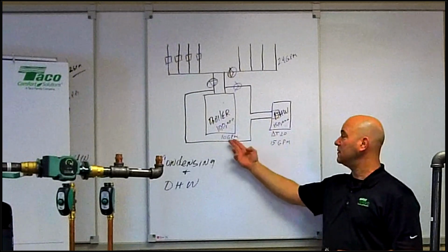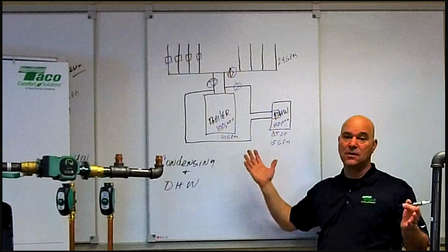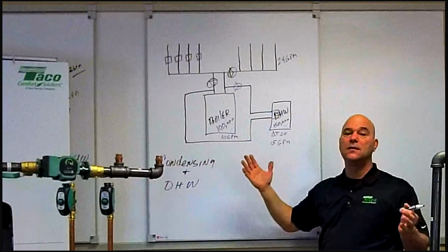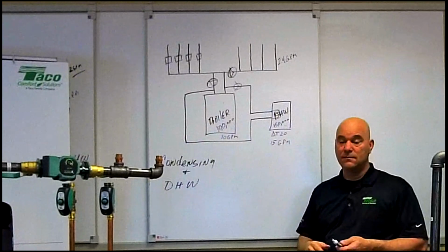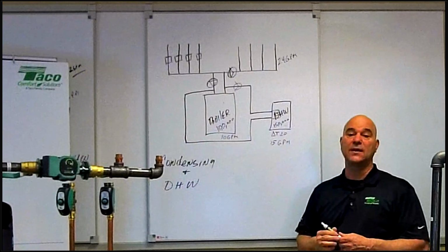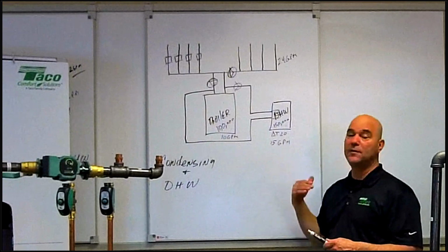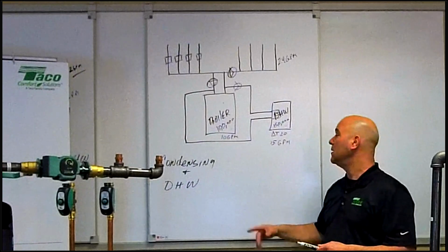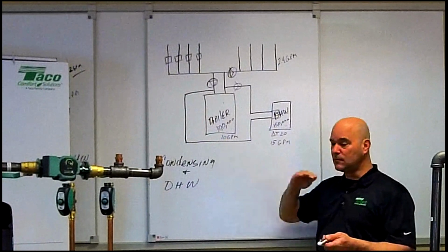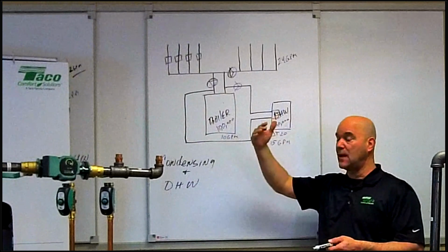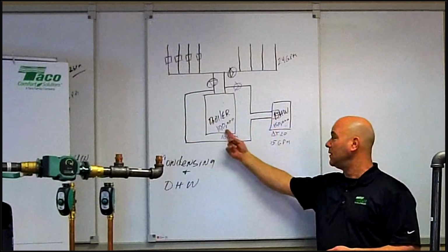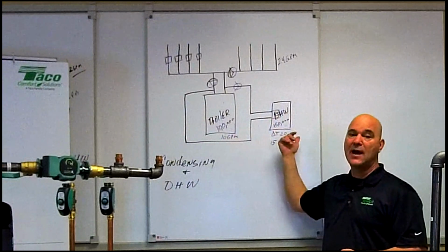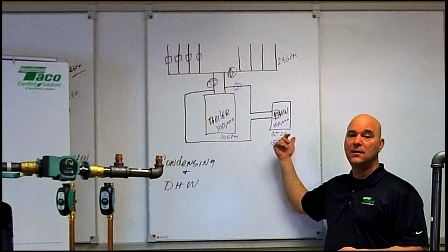In this scenario, really all I have is 100,000 BTU to move. So I can size it for 15 GPM. It's going to take my delta T and shrink it a little bit probably because I'm moving more water than I need to. But reality is, if it puts me up to a higher volume circulator that costs more money, I really only have 100,000 BTU to drive to this indirect.